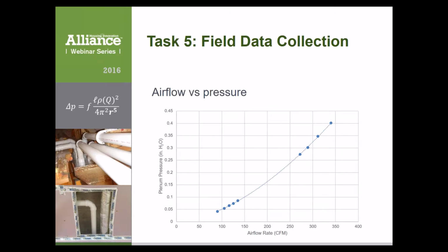Because we've shortened the total duct length, the system is going to be installed centrally in a home. So we're not talking about a 50-foot long duct run to the other end of the house. It's all short, compact, and central. And then also because it's smooth walled with smooth elbows and transitions, the total static pressure has actually been maintained at a pretty reasonable level.